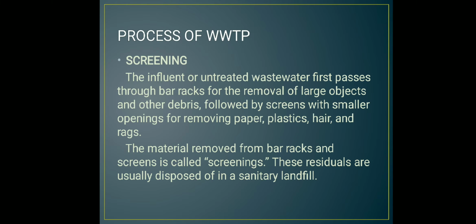Screening: the influent, or untreated wastewater, first passes through the bar racks for the removal of large objects and other debris, followed by screens with smaller openings for removing paper, plastics, hair, and rags. The material removed from bar racks and screens is called screenings. These residuals are usually disposed in a sanitary landfill.